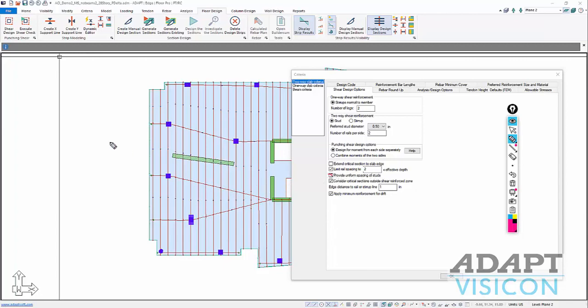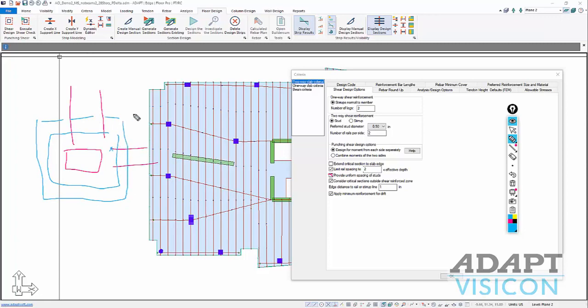Now in legacy look at the program and the way this was treated in previous versions, 2017 and prior, if we have a column and we need studs on these rails on the column, the program would always treat these in terms of sections, or what we call layers. So the program would check layer 1, which is d/2, layer 2, which is again d/2 from the previous layer, and so on. And between each layer, we determine what is the requirement of studs here. This is for L1. What's the requirement of studs in this gap, d/2 in spacing.